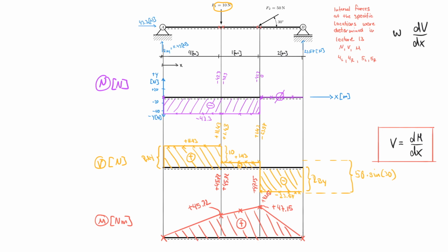And the reason I have not included an equal sign yet is one very important aspect. And that is something that is probably the reason why you did not see that this really is the derivative of this load case, or sorry, of the shear force diagram. It's because this is actually the negative. So the arrows here are pointing downwards, and therefore the W would have to be negative here. So this is negative, and now it's equal. So the inverse of the derivative of the shear force is really the load case. So if you want to put the minus on the other side, that's what that would mean.